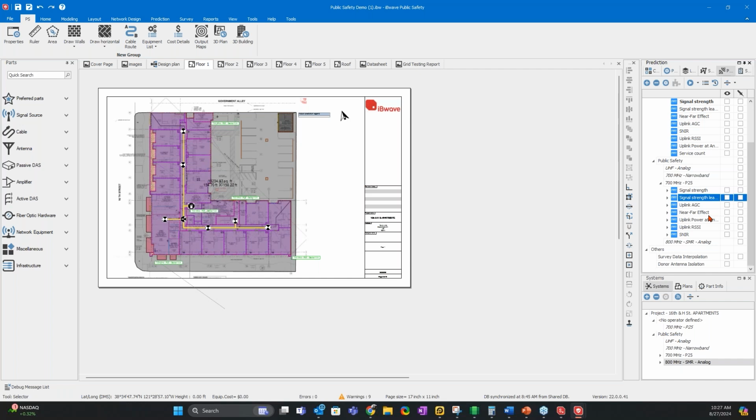So what happens? Think about I'm far away from an antenna, transmitting, barely making it with the maximum gain of the BDA, right? And suddenly somebody very close to a coverage antenna like this one up here keys in. In public safety, keying in means you start talking. What's going to happen to the BDA? It says, hey, you're coming in too strong, reduce the gain. Reduce the gain. What happens to the guy who's a little bit far away? His call drops. That's called the near-far effect. So somebody near is affecting somebody far away, right? It's a very common thing, and that's the reason a lot of AHJs want more antenna density or better gain.